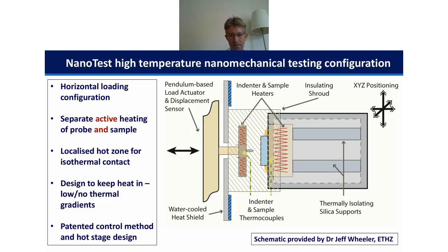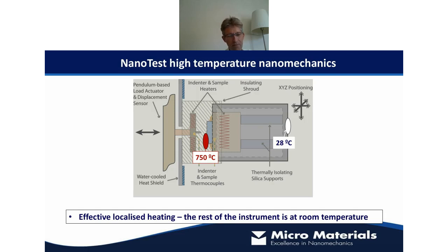The stage itself is patented as well. You can see there these thermally isolating silica supports, and what they do is allow the back of the indenter stage to be really at room temperature, sort of 2 or 3 degrees higher. If you put some thermocouples on when you're up at say 750 or 800 degrees, you can confirm that you're basically at room temperature at the back of that stage.